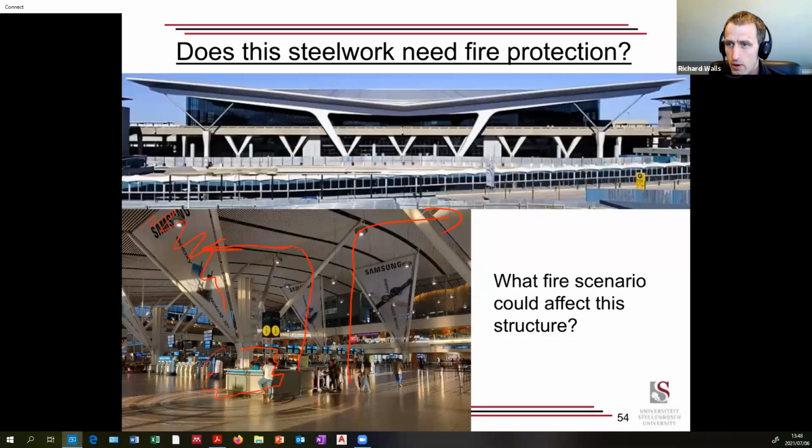But often there are cable racks or just structural systems that are not carrying load. And also if you've got purlins, etc., as soon as you have thin steel, protecting it is such a mission. And often if it fails, so what? In certain structures, if the sheeting fails, the fire vents up the top and the fire cools down because the hot air goes out the roof, but it will vary from structure to structure.